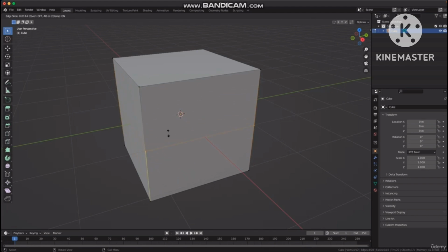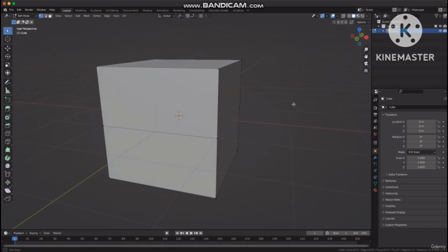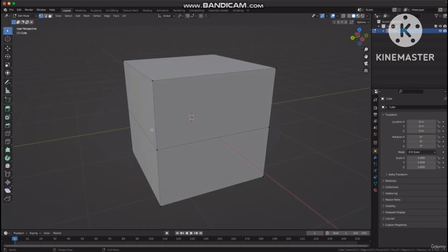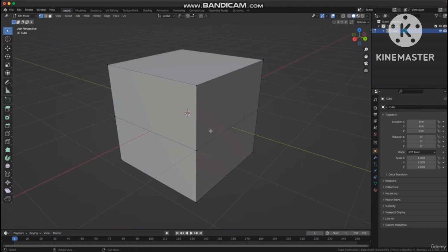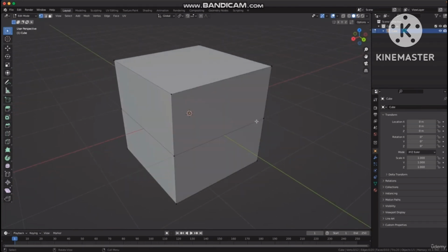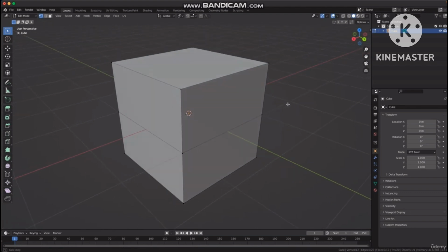And now I can actually adjust where exactly you want to create that cut. If you want to leave it in the center, you can just press escape and it's going to snap to the center. And then just click anywhere in the 3D viewport to apply that. And I can see we have created this edge that goes all around our object. So let's create another loop cut.